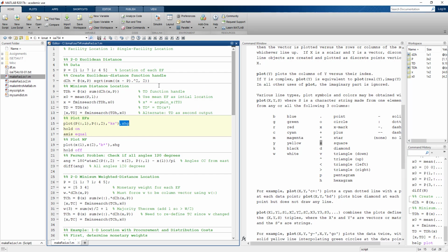And what this does is, in this area right here, if I plot it, the first time I plot it, it automatically puts the window in the front of the MATLAB screen. But later on, if I go back and start doing something in MATLAB, it gets hidden by all of this. So if I want to see it again, one option would be to click on the icon of the figure and have it display at the front.